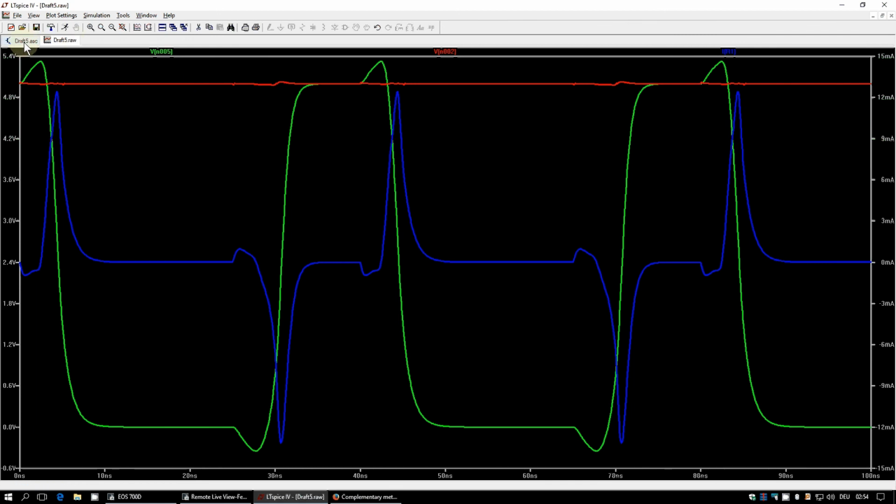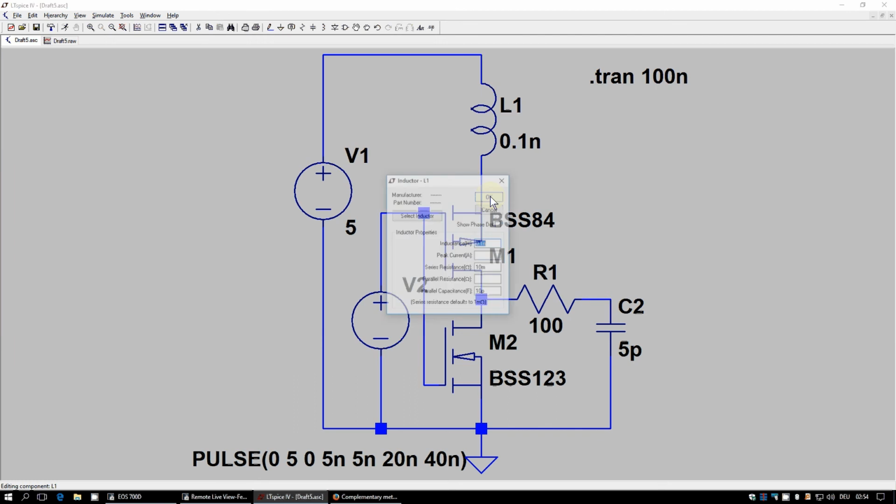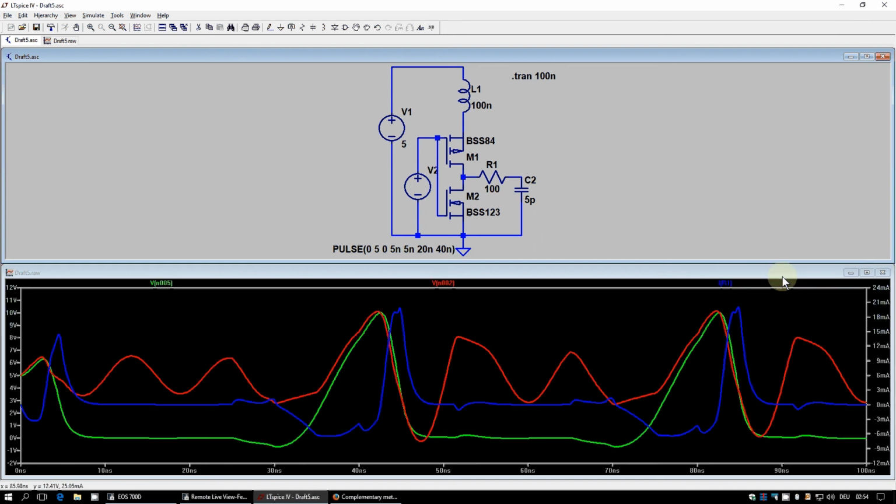But now let's change this inductance to a more typical value, and let's really do a very long and badly designed copper trace of 100 nanohenry. You can get this already with 10 centimeters of PCB trace from your regulated voltage supply to your IC, and 10 centimeters is not uncommon in PCBs, especially if you're using through-hole parts instead of SMD, which are more than 4 times larger. And look what we get now.